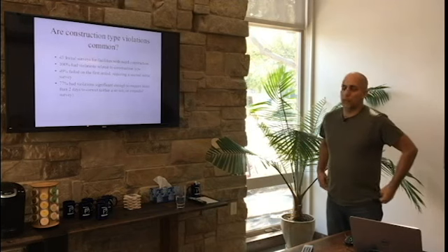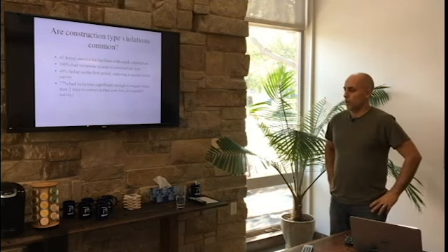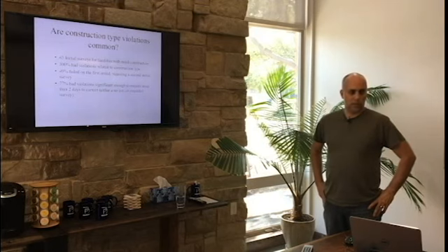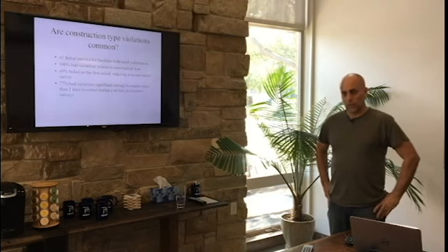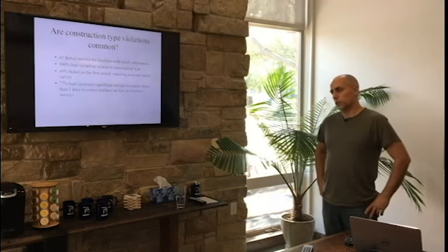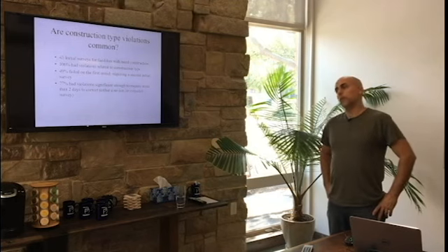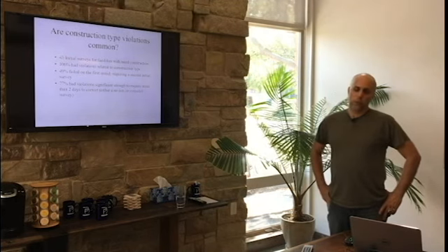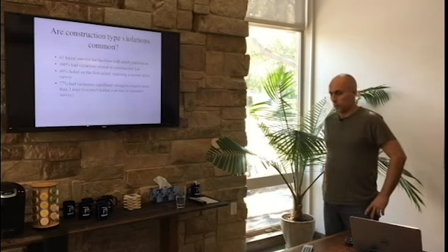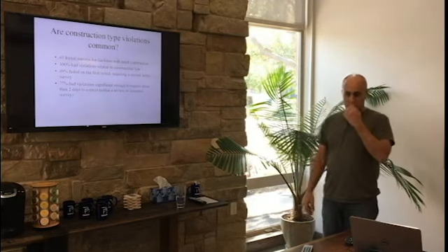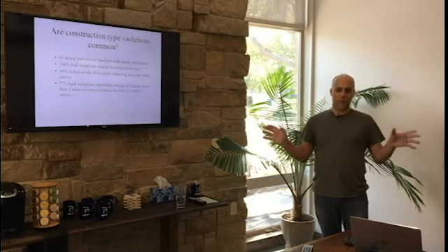And that's why in healthcare facilities especially, we have so many different systems, passive and active, that overlap each other. It's that redundancy that we rely on. Is, well, why do we have to do this if it's sprinklered? Because the sprinkler system is going to fail. You have to assume that. Okay, well, why do we have to do the sprinklers so perfect if the fire alarm is always, because the fire alarm is going to fail. You have to assume that. So the assumption is that everything is going to fail in your building.